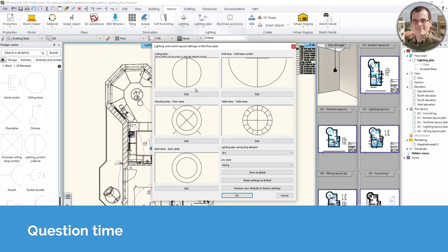If you have saved your groups into the corresponding libraries, then you can browse them in from this dialog. And once you have done that, you can save it as a sort of global setting. From that point on, next time you're pulling up this dialog, this would be the default. I'm not going to do that now because I don't want to override that nice X-shaped form, but this would be the idea. This will be the answer for how to make this default for your country.